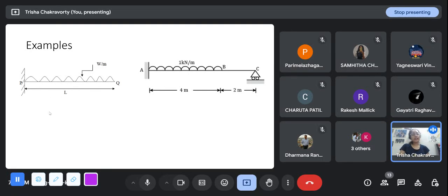Similarly in this, if we eliminate the x direction force and displacements, then there will be two unknown forces here and one unknown force here, and we have two equations here. Because if it is a beam element, we have only two equilibrium equations, because summation of Fx equal to 0 is by default satisfied, since in a beam element there is no axial force, so summation of Fx will always be 0 and it is a redundant equation. So we have basically two equations: summation of Fy will be 0 and the summation of moment will be 0 about the axis out of the plane. So we will have two equations and three unknowns, two here and one here. So the degree of indeterminacy remains 1.